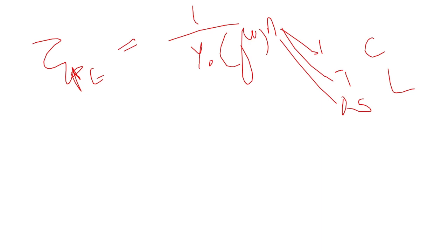We saw there are 7 processes involved. One is cation interstitial generation, where the metal goes into the film as a cation interstitial, a vacancy is created in the metal, and an electron is released. Then cation interstitial consumption was another case, where the cation interstitial diffuses through the film and reaches the film solution interface. That was another case you saw.